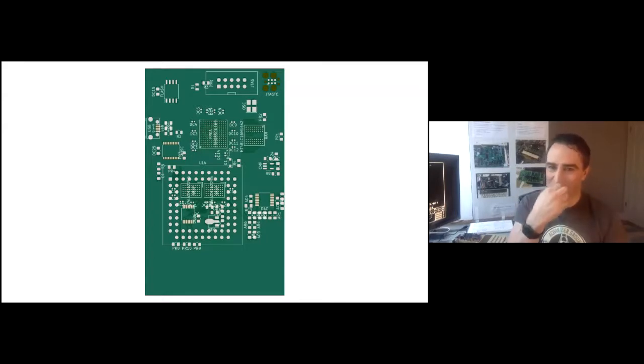So I started out with the ULA footprint, and it's based on the board from Dave Hitchens, his breakout. Figured out the pinout and everything. So it's the same size as that. I believe it's the biggest board that you could fit into the Electron without covering the RAM chips, and without interfering with a master RAM board.